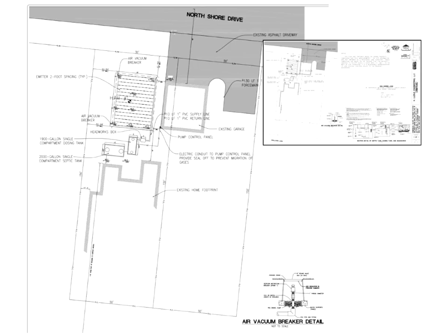Actually, Rodney, if you want to just do a quick tour through what you're seeing there, that's an actual as-built drawing of the subsurface drip dispersal system in the heavily sandy areas of northwest Michigan. If we look at this, this is a septic tank, and then it's going straight to a dosing tank. So this is primary treated effluent. It's not secondary treated effluent, which is fine.